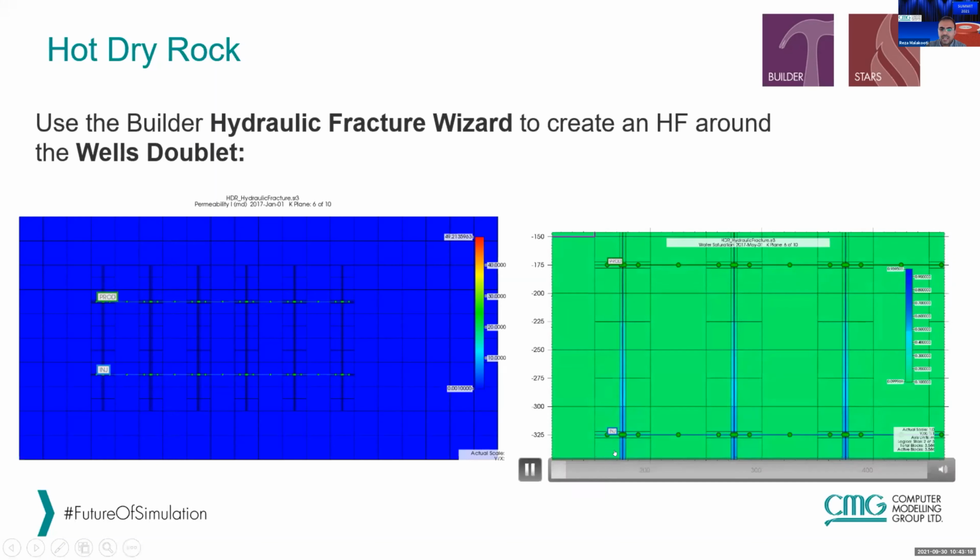If we just look at the first picture in here on the left-hand side, in these closed systems with a single well configuration, people inject the cold water into the annulus, and there would be no perforation or communication between the well and the reservoir. It would be completely a cased hole well. And then as soon as that cold water comes in contact with the hot reservoir source, it will be heated up and then produced back from the tubing.